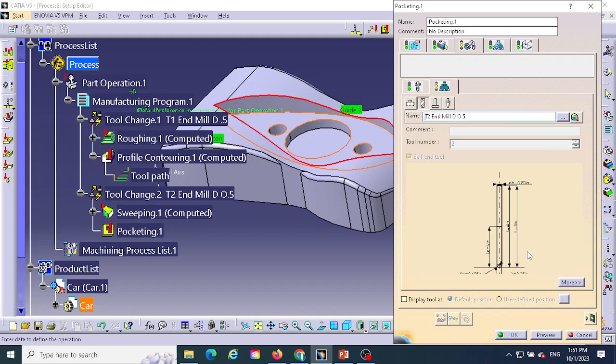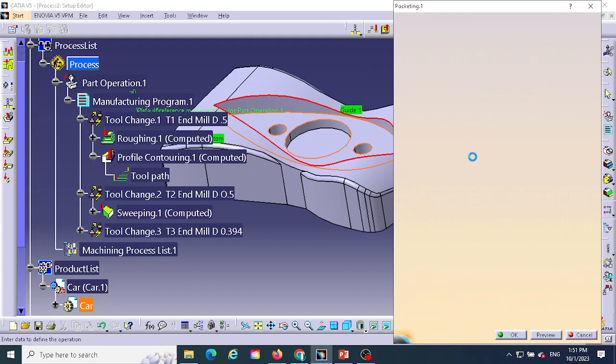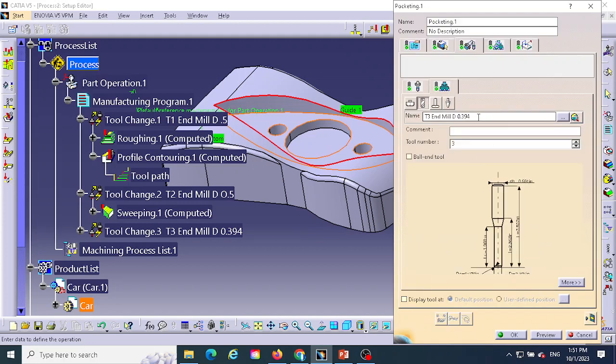The tool cutter, you can choose this one, but it should be an end mill. Of course this is an end mill, as you can see. So we can use 0.5. I think the previous one, you can use 0.25.